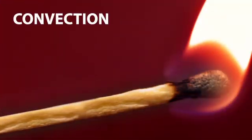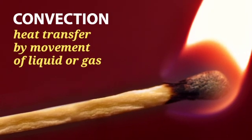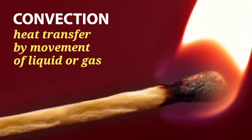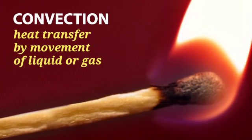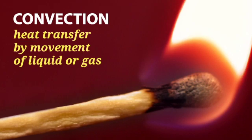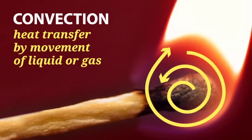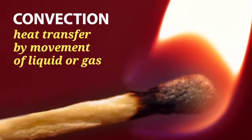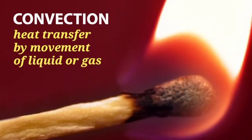Convection is another form of heat transfer, and it is defined as heat transfer by movement of liquid or gas. The flames that you see in any fire are produced from gases that are ignited during combustion, and thus are examples of convection. You can see this as you look closely at a burning match. As the match heats up, the wood breaks down and produces volatile gases. The ignition of these gases is what produces a flame. Convection would also be responsible for the heat you feel when holding your hand over the match but not touching the flame.